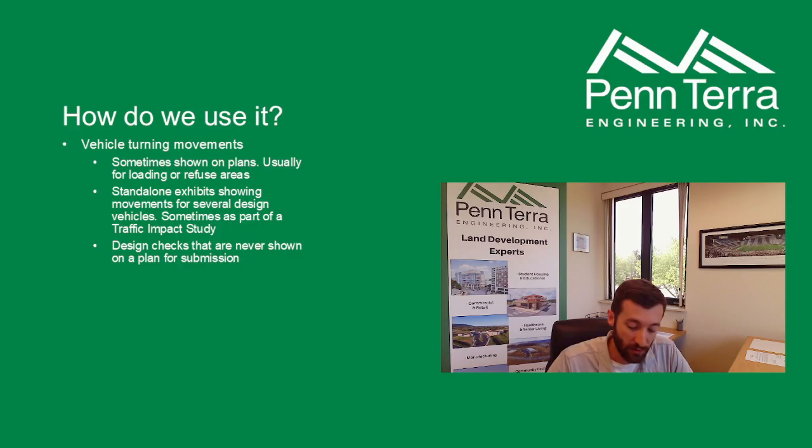and we use them in a variety of ways. Sometimes we're required to show them on our plans, usually to show that the loading areas or refuse areas can work. Sometimes we also have to do standalone exhibits showing movements for different vehicles. We've been doing them lately a lot for traffic impact studies and then providing them to our traffic consultant. And a lot of times we use it just as a design check during the process of laying out the site, to make sure whatever delivery vehicle or fire truck or garbage truck needs to make it through the site is able to do so. Maybe it doesn't actually end up on a plan, but it's a good way for us to make sure our layouts are good.